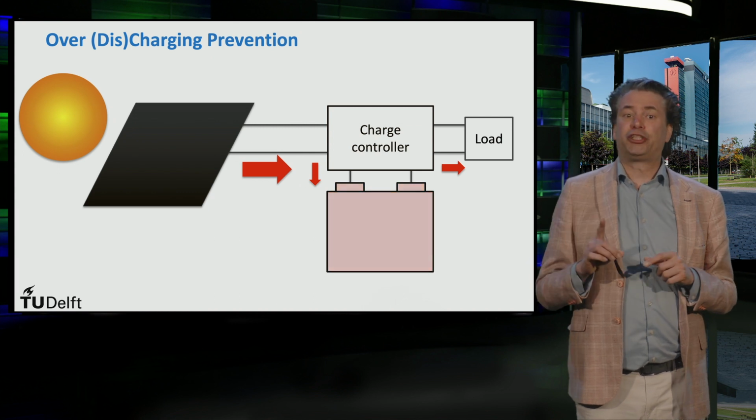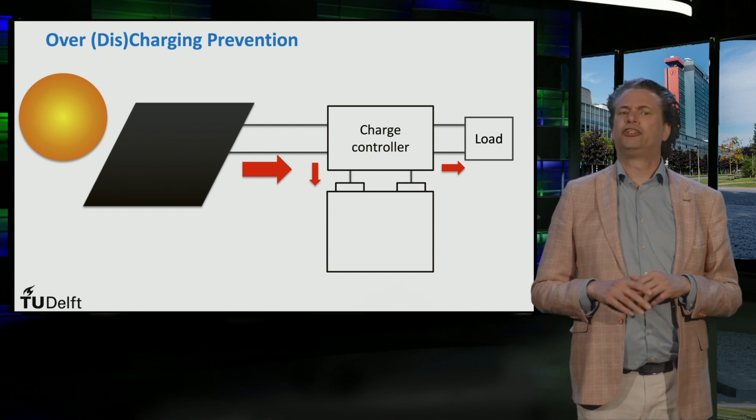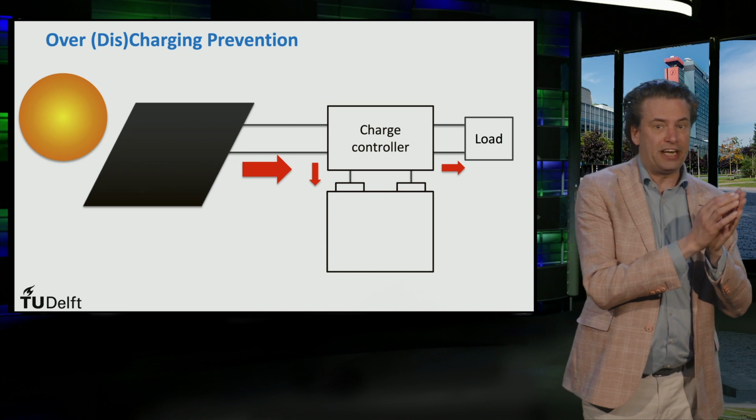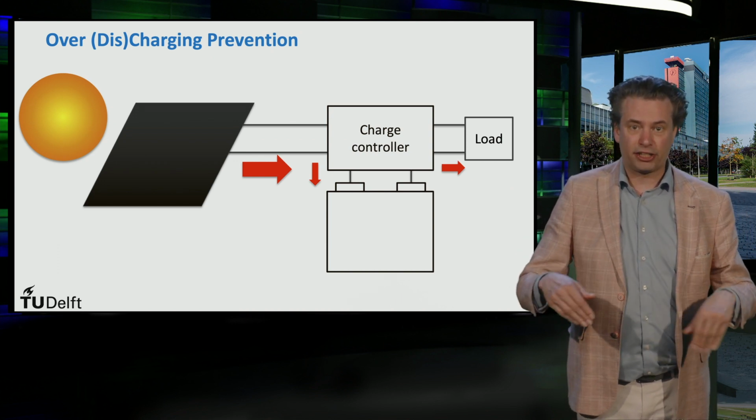But with the help of a charge controller, this problem is avoided altogether. Here, the charge controller plays a vital role by decoupling the PV array from the battery, thus stopping the battery from being charged any further.